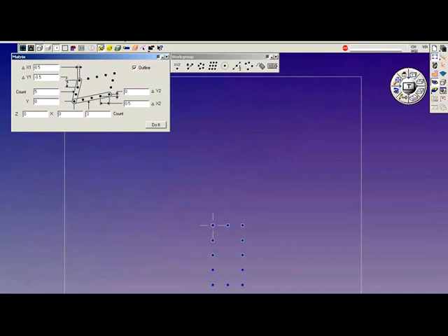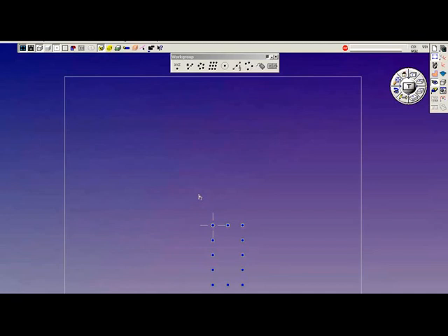So you can use any of those initials or letters to do math or trig functions in any dialog box. It doesn't have to be this one in particular. It could be any dialog box within the system. So it's pretty handy for doing your calculations in the dialogs when you're creating geometry. I'll go ahead and close this up. Delete the matrix from the screen.